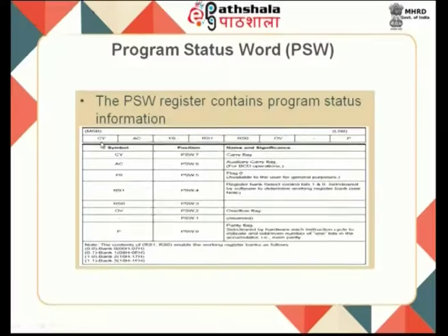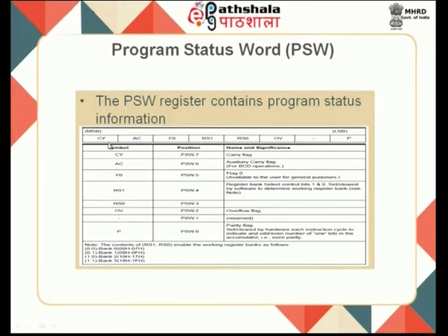The first bit, that means the 8th bit, the MSB, if it is 1, then I say there is a carry. I call this PSW.7, and this is the carry bit, otherwise called the carry flag. If a carry occurs while I am processing, then this bit is set to 1.